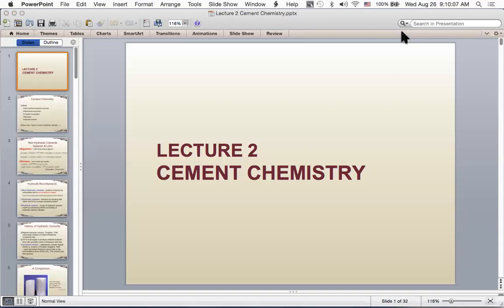For example, C3S will react much faster compared to C2S, although the hydration products of these two will be similar. On the other hand, C3A will react super fast with water, and the hydration product is totally different. So we have to know the percentage of these 5 major compounds, so we can predict what the end product will be. We need to know the percentage for each compound before we use it. Yeah, good question.